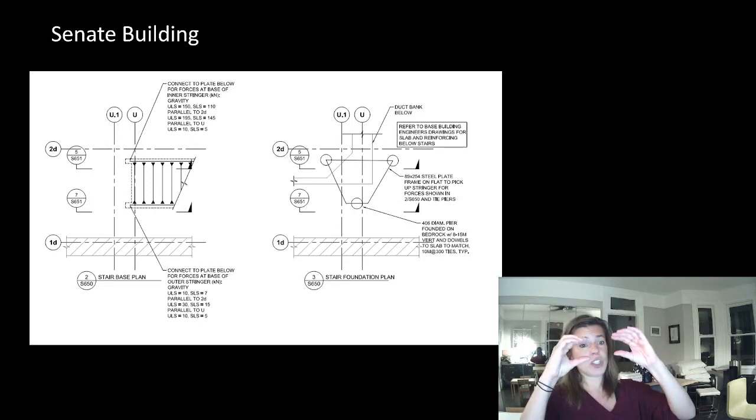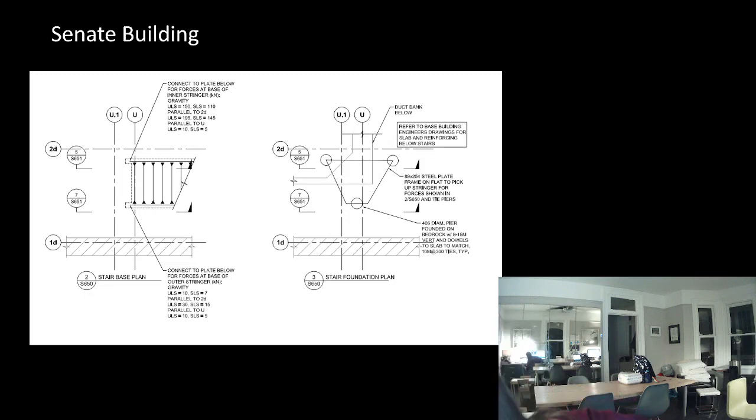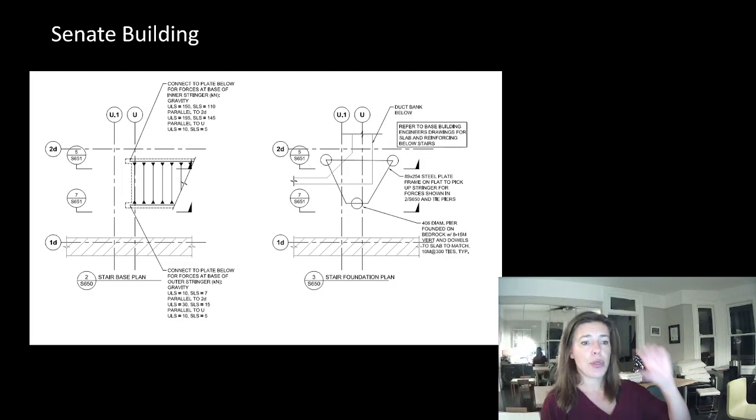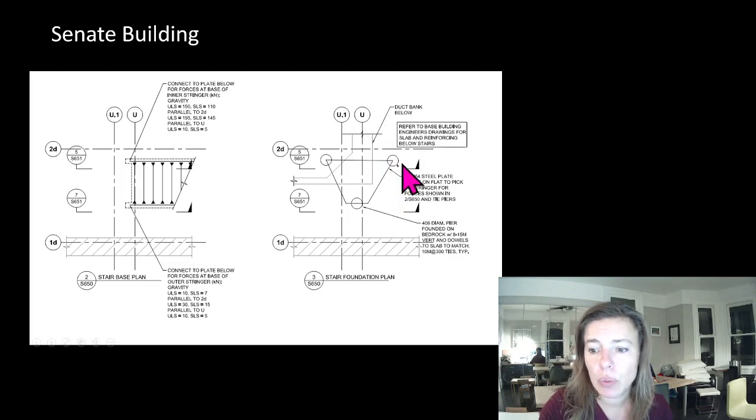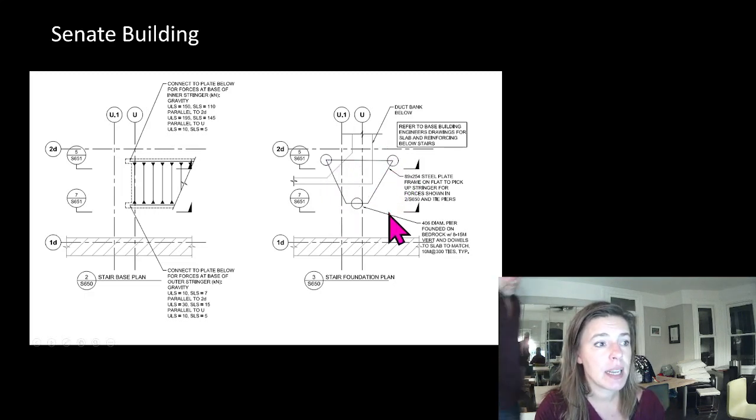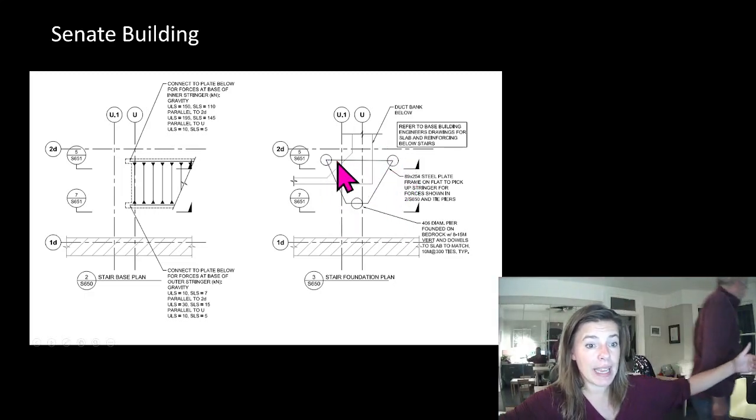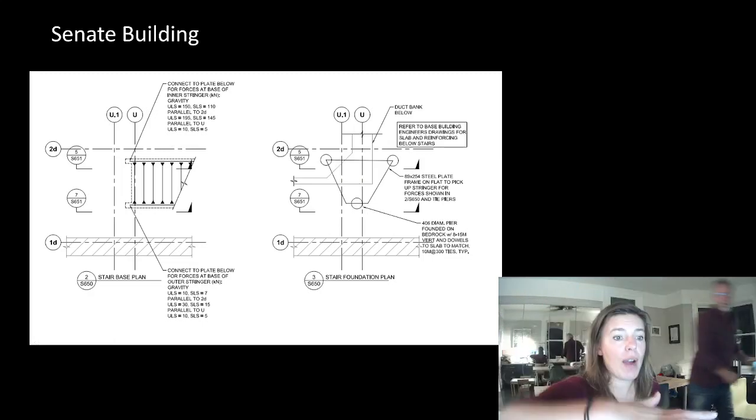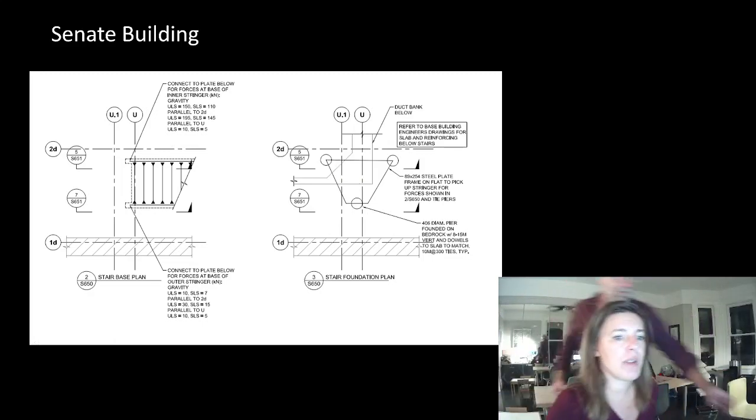So literally it was just a big thick steel plate. What size is that plate? Yeah, it is 3.5 inches thick by 10 inches wide, welded to plates on caissons. So this is just a big steel plate frame to develop the gravity loads and our thrust loads.